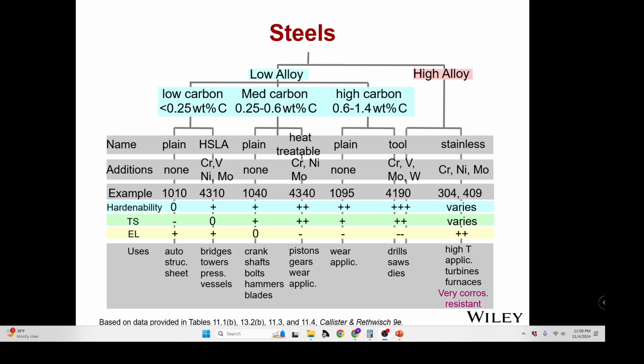So they're very high in hardenability, very high in tensile strength, very low in ductility. So things that can't take a lot of impact abuse, exactly, but they're very high in terms of tensile strength. They're also very good in compression as a result of that. So you'll see a lot of internal engine parts made of 4340 steel.